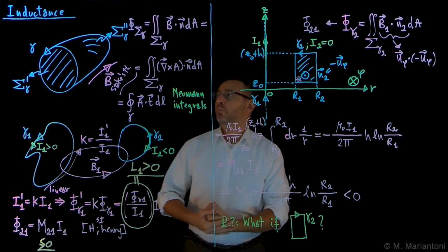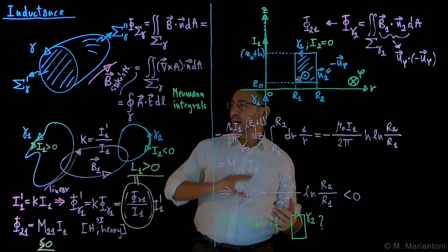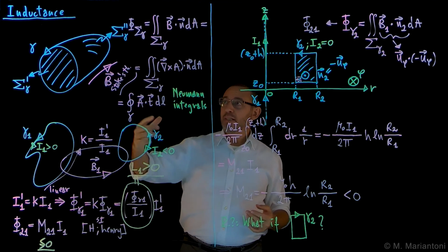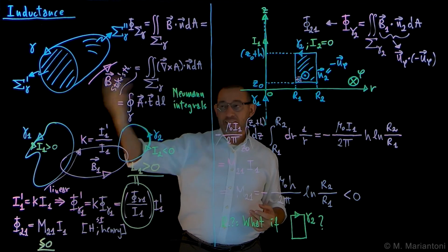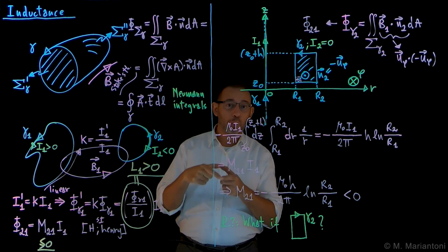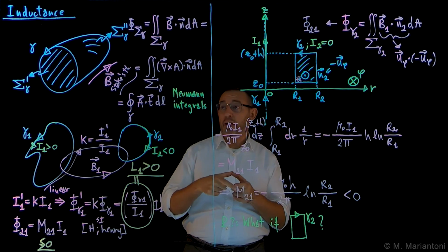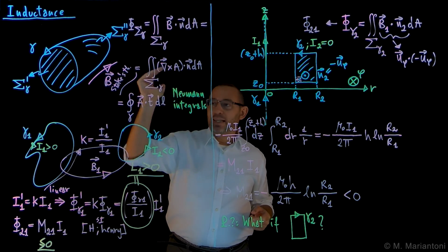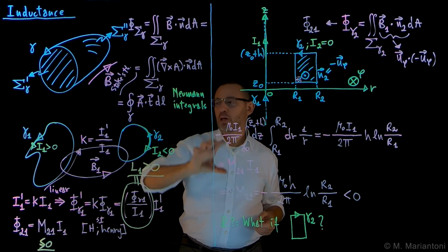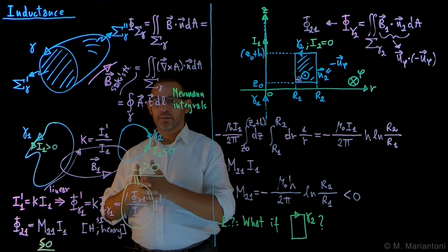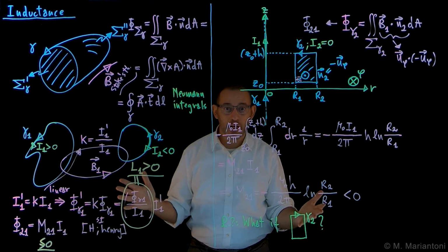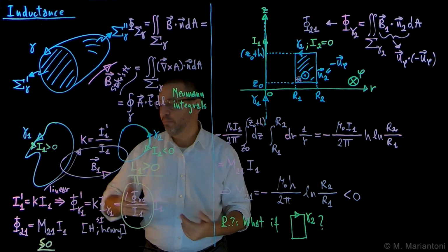So to summarize this video, I wanted to give you a refresher about inductance, which we've seen in 242. The first thing which I wanted to stress is that the flux due to a magnetostatic field B is independent from the surface. It only depends on the border that an infinite set of surfaces share. And therefore it can be calculated as the line integral, the circulation of the vector potential. We will use this in normal integrals. Then I introduced the concept of self-inductance, which is the ratio between flux and current. It is universally a constant, which we call the self-inductance, with units of Henry.